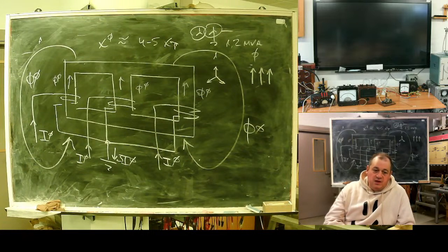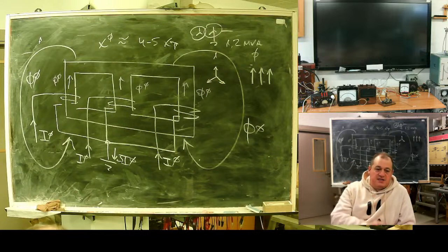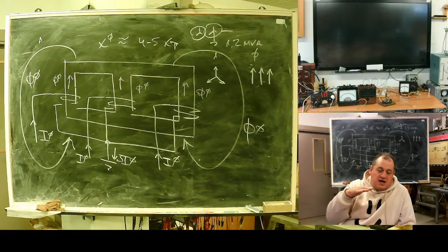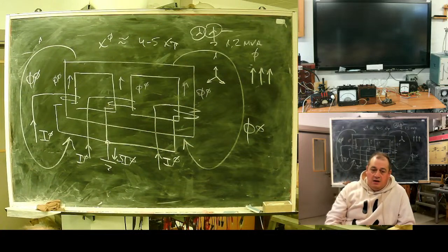Second problem: in case of non-symmetric load, zero sequence magnetic flux will close in the transformer's vessel, and there is a weak point where the roof is attached to the main vessel. It has oil-tight sealing and a set of bolts. These bolts can overheat and burn out the sealing, causing oil leak and fire.